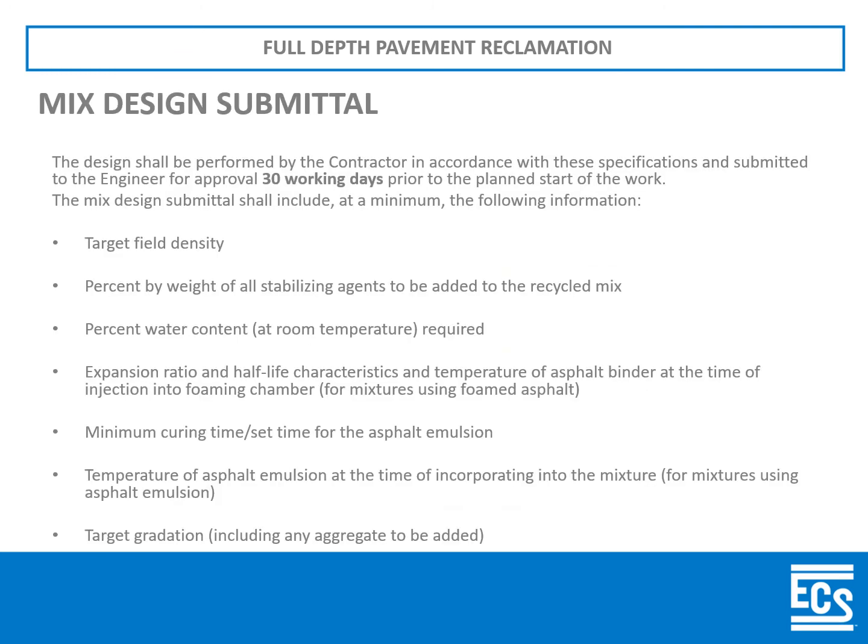Now, the mix design submittal, this is where it's very critical. As you can see, the mix design submittal is supposed to be submitted to VDOT or the engineers 30 working days prior to the planned start of the project. At a minimum, it should include the target field density, basically your proctors, and the percentage weight of all the stabilizing agents, so they can see what range of cement is going to give you the optimal strength requirement.